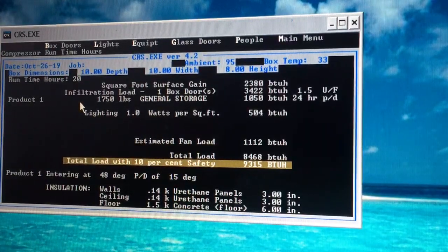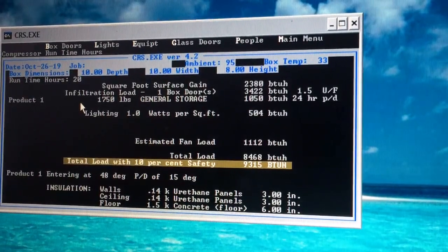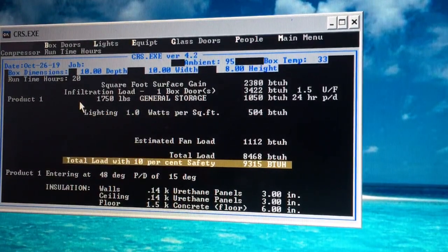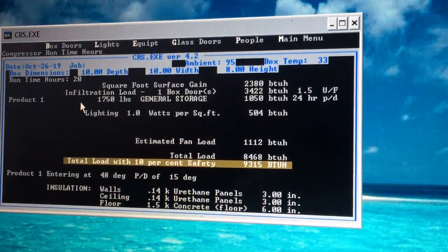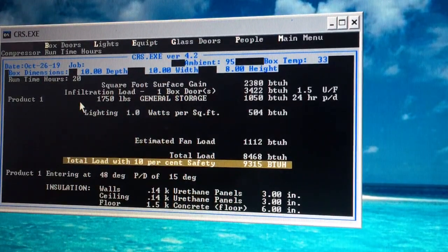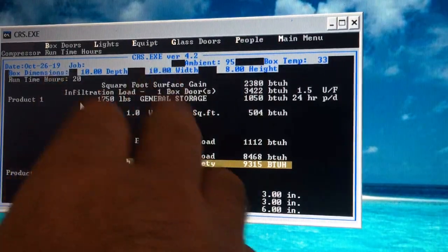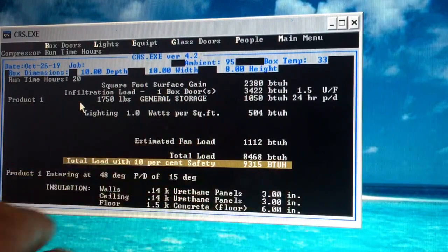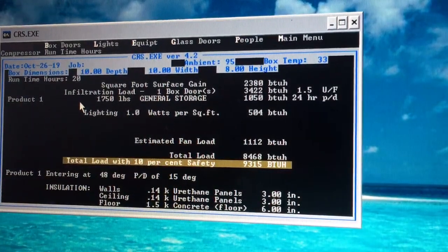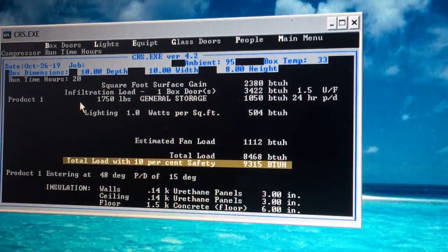So somewhere between 9 and 16,000 BTUs, basically, you can size the box anywhere between there. Experience will tell you. Choose the midway point. If it's always a cold location, you can go with lighter usage. So it's going to be somewhere between 9 and 16,000 BTUs.